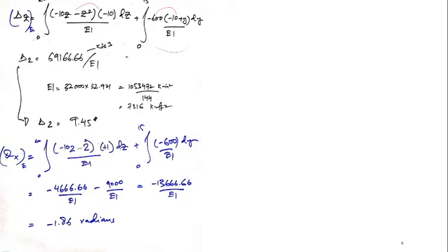So finally I've also calculated the magnitude of EI. This is 32,000, given, this is also given. So I've got this value, and this is actually in kip square inches, and I've converted it into kip square foot. And finally I've got 9.45 feet. It's a huge magnitude of translation. But you should know why it's so great, because there is already a load here. You can see that there is already a load here at the free end.